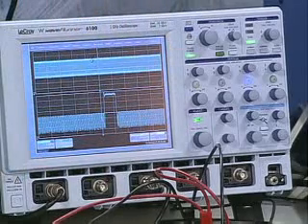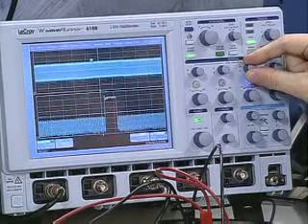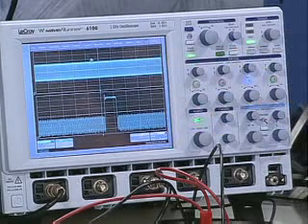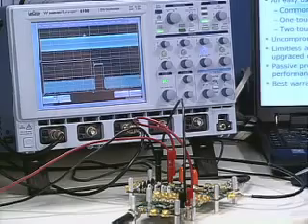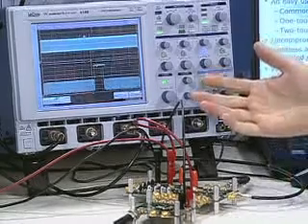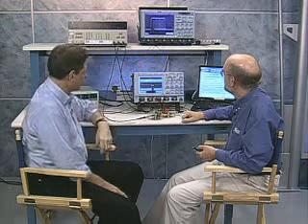That's wonderful. So in fact, if you change the offset here, you can move it up and down. What we've got here is a signal from a laser driver. Actually, it's a nice National Semiconductor part. And it's making a string of pulses, and we've zoomed in on the bottom on a particular pulse that we're interested in. In fact, we captured this in a single shot. Yeah, we've got all the data captured, we're just looking here at this one little tiny thin pulse out of all that data.